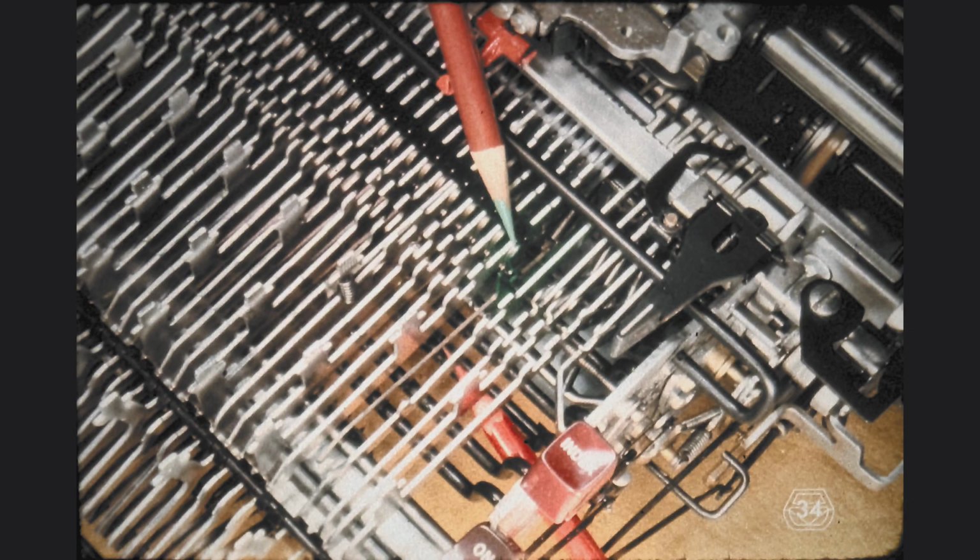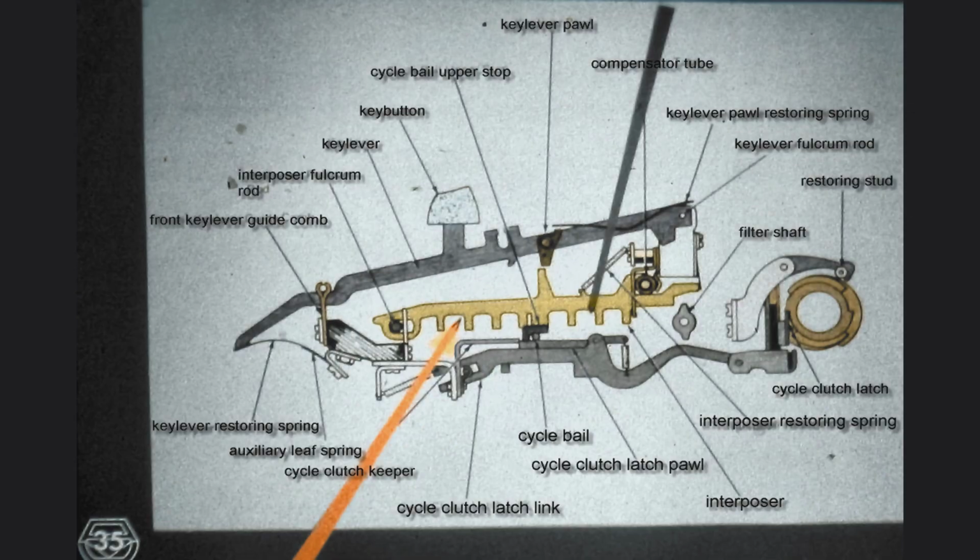Take a good look at the interposer lugs from underneath the keyboard and convince yourself that there is only one interposer of a kind. Interposers differ from one another by the quantity of these lugs and their relative positions. As mentioned earlier, the indicated cavities are occupied by selector bales, and as you know, there is one selector bale for each selector latch.